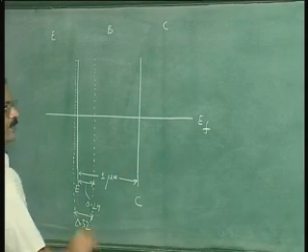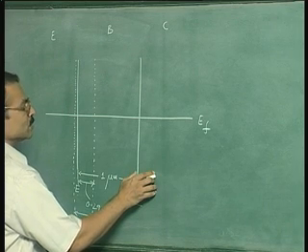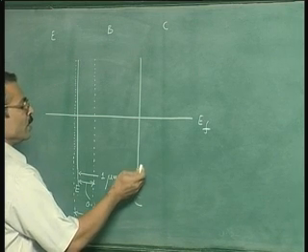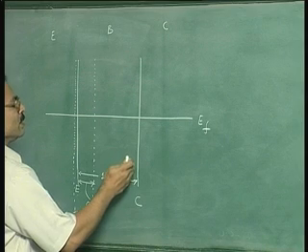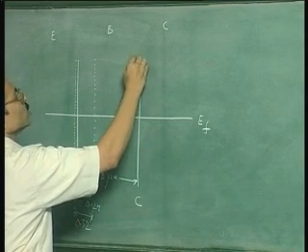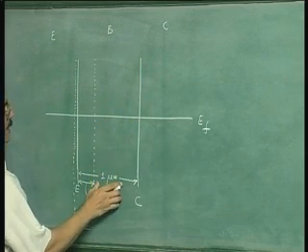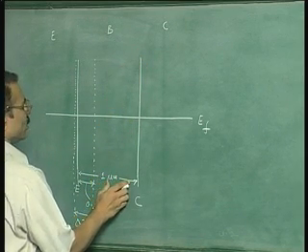Similarly, on this side the depletion width is 0.94 microns, out of which 0.085 microns is on this side, because collector is lightly doped compared to base. So 0.085 is about 0.1, 0.1 is 1/10 of this, less than 1/10 of this.